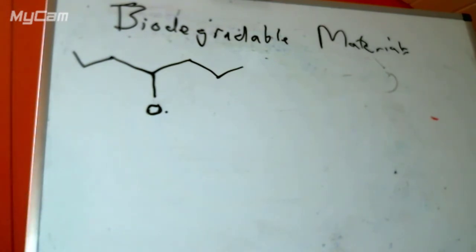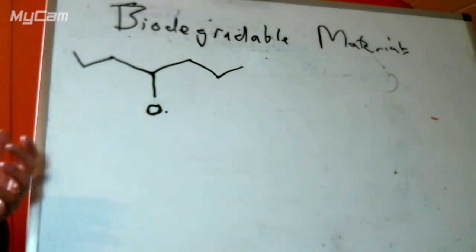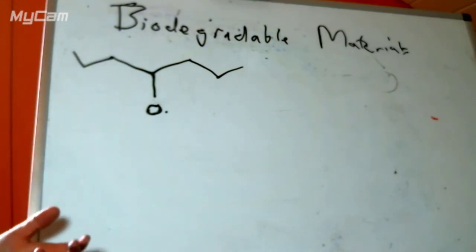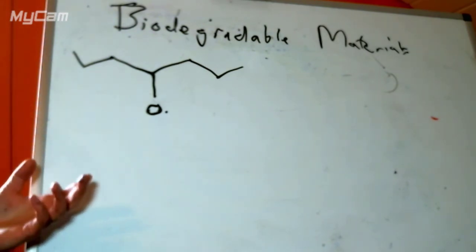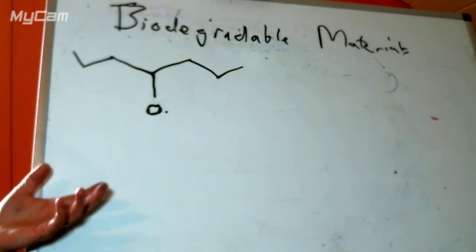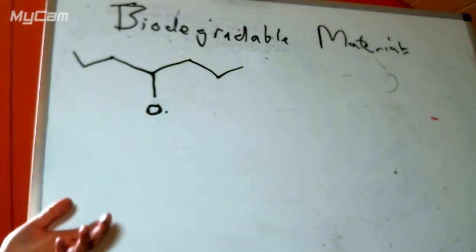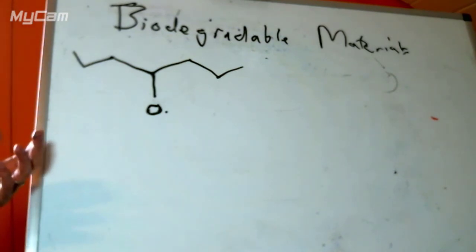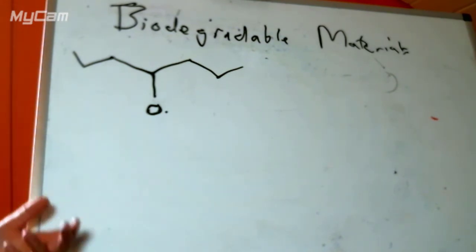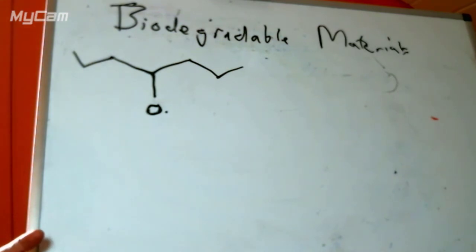Obviously, they are great materials, but there is a problem. If we mix them in with our normal waste, then we're going to be mixing catalysts into our recycled material. We can throw in extra antioxidant and that will make it usable, but it will reduce the number of times that we can recycle it.